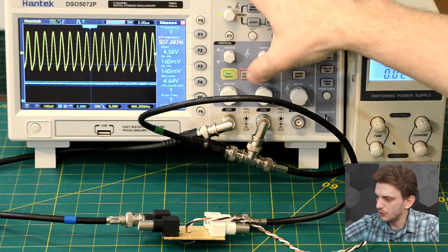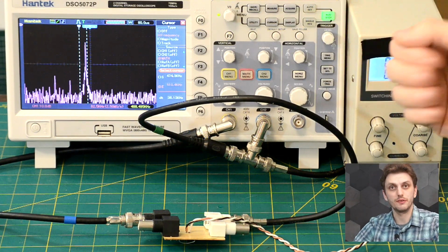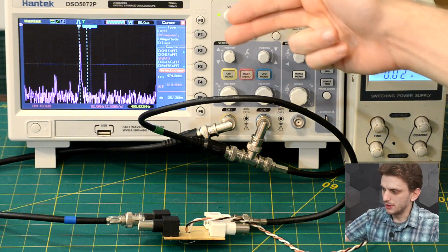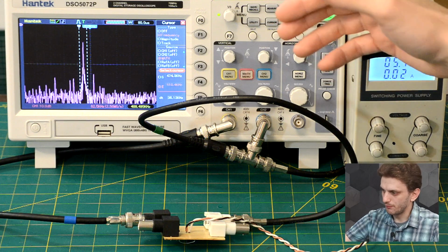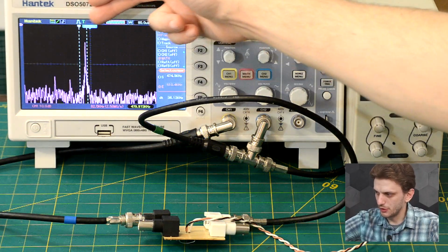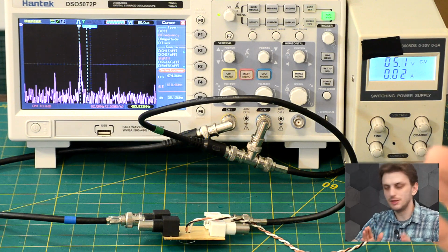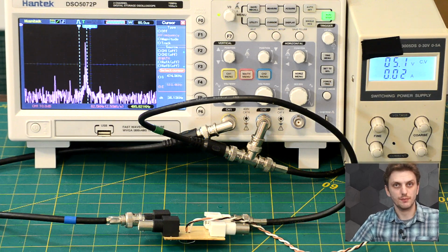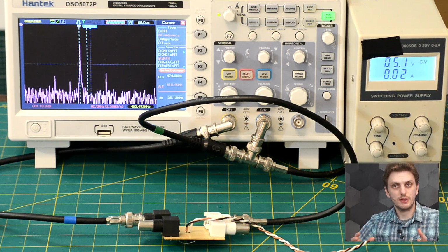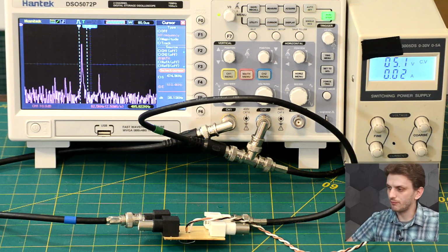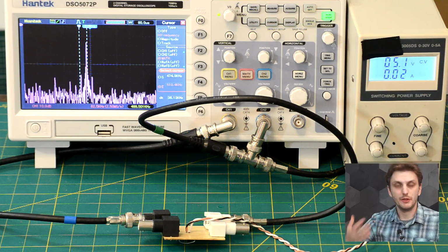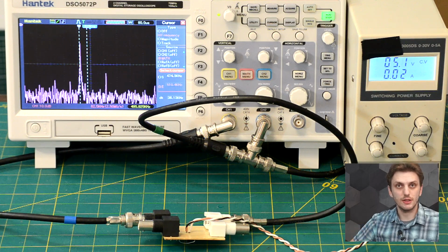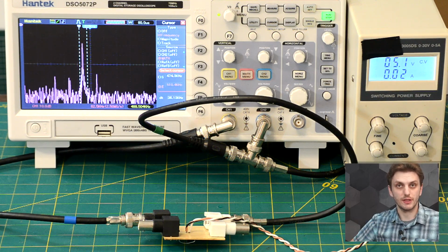We could get a better view of this if we turn to an FFT spectrum. So what I have here is a zoom in on our output frequency, and I set my two cursors so that the signal goes in between these, and well, it goes between 470 and 510 kilohertz. So not a big variation, but in certain cases this can be enough. And of course this can be improved by using different components in the oscillator or with different types of varicap diodes. So now let's turn to the other circuit, to the relaxation oscillator.